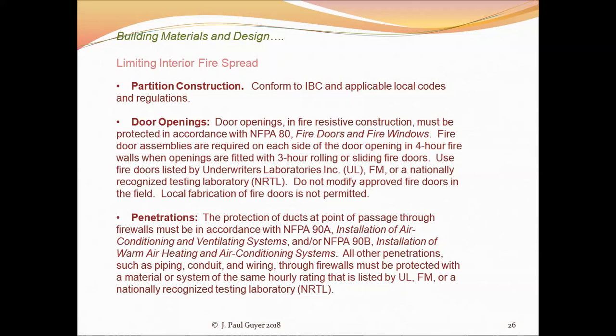If the barrier, the partition between the one occupancy and another occupancy is required to be of 2 hour fire resistive construction, then there needs to be a fire resistive barrier incorporated into the ductwork system and the air conditioning system. And this is typically a damper, an automatic damper.